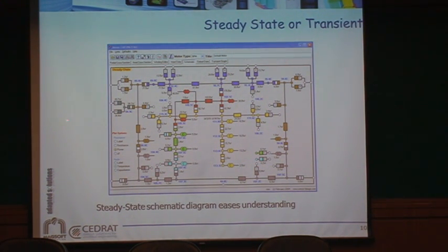So this typical machine here, which I think is the default, at steady state we get about 100, 110 degrees inside the winding. If I look at the stator here, it's a little less than about 100, 105. Then I go to the housing, 90, etc. So I can actually follow all the paths of the heat.